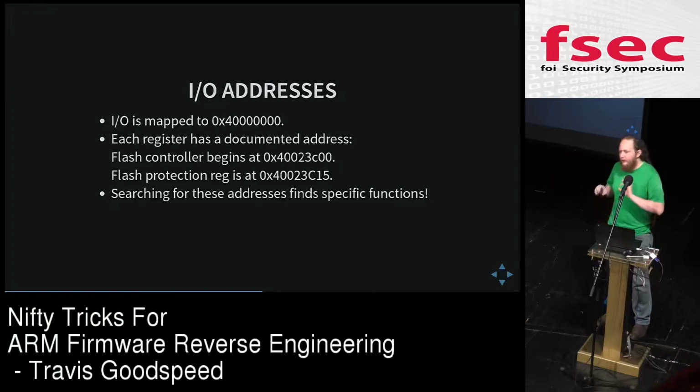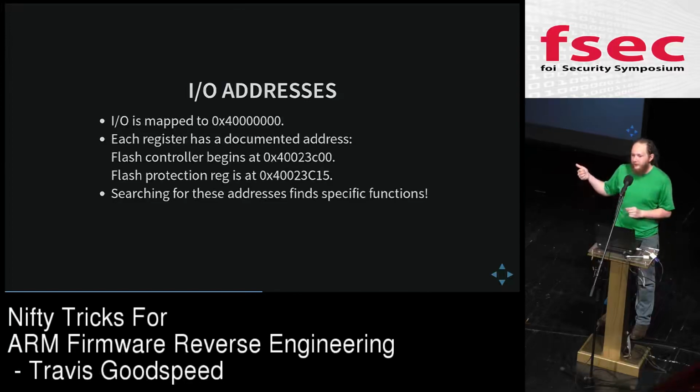Now, when you're reverse engineering PC software, you have clues such as system calls. So you can look at anything that calls the right system call. That has to involve I/O. You can also look at shared libraries. So if it's calling printf, you know that it's going to print something to the screen. You can then look for error messages in order to figure out what particular functions do and work your way backward from that. But on an embedded system, you can't do that because there are no symbols distributed in the product. Everything is perfectly statically linked, and there aren't any system calls because there is no operating system.